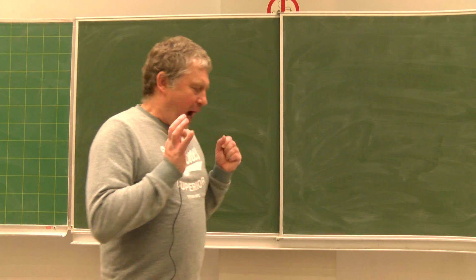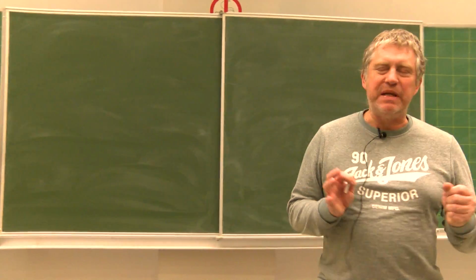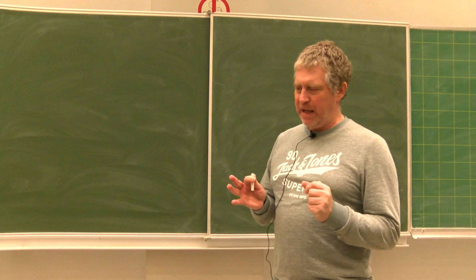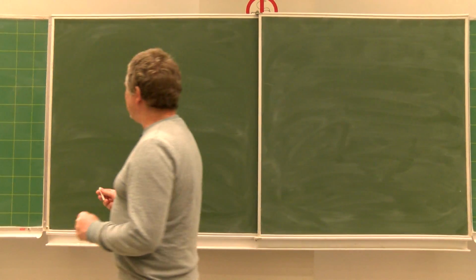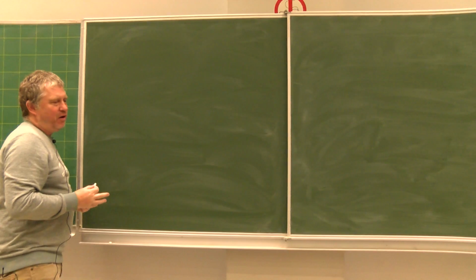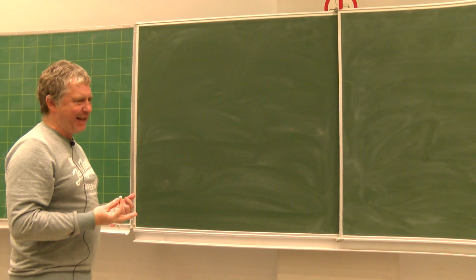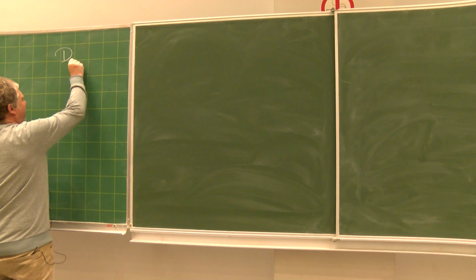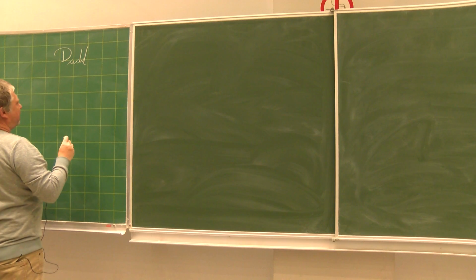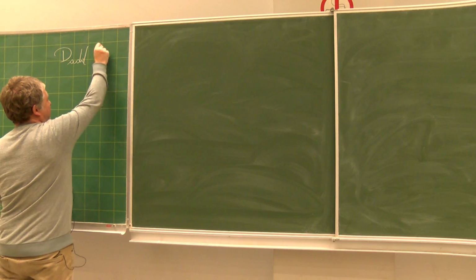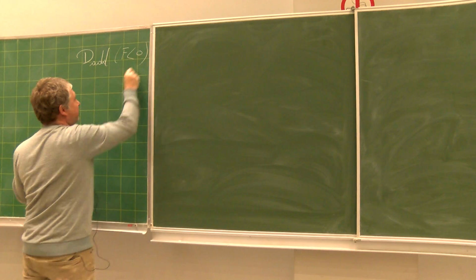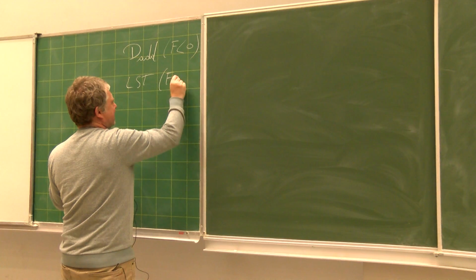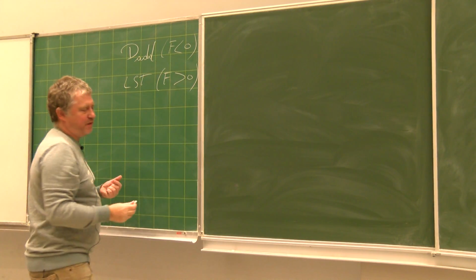So, I was busy last time with the air intakes or inlets with the external flow. And we explained that there are two forces that we need to add to the problem. One of them is what we have called the additive drag. And this is a drag, so this is, let's say, a negative thrust. And another one is the lip suction thrust. This is, let's say, a thrust, so this is a positive thrust.